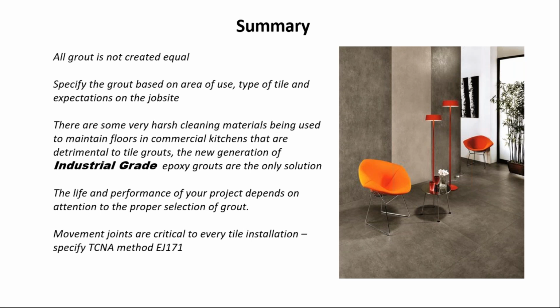Portland cement grout can stain and can effloresce. Even on a properly mixed and properly installed job, with heavy rain on it, you can have efflorescence. Is that the installer's problem? No, it's the nature of the beast with a Portland cement grout.